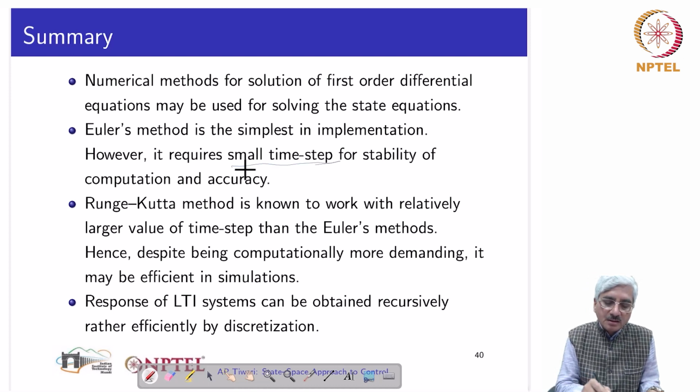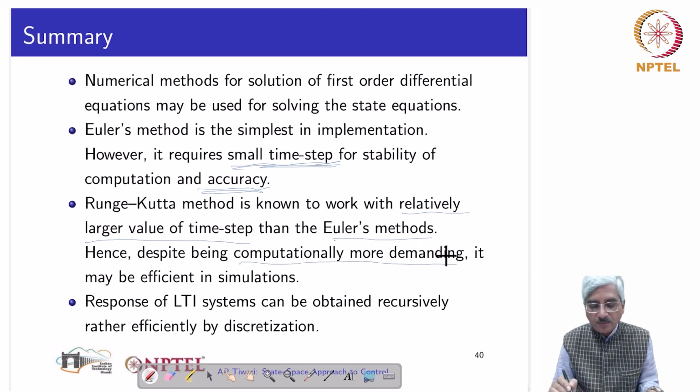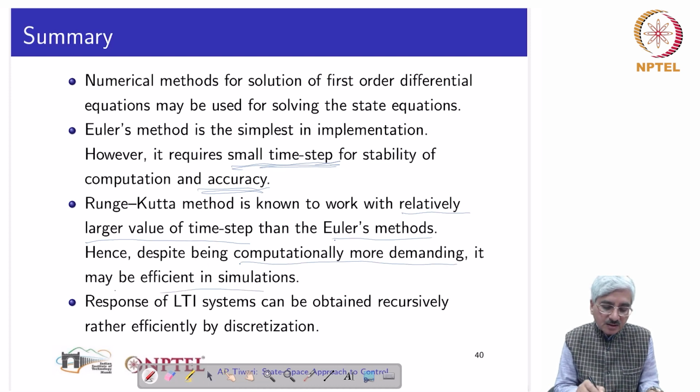However, it requires small time steps for stability of computation and for achieving accurate solutions. The Runge-Kutta method is known to work with relatively larger values of time step than Euler's methods. Hence, even though it is computationally more demanding and more complex compared to Euler's method, it can be efficient in simulations in most situations.